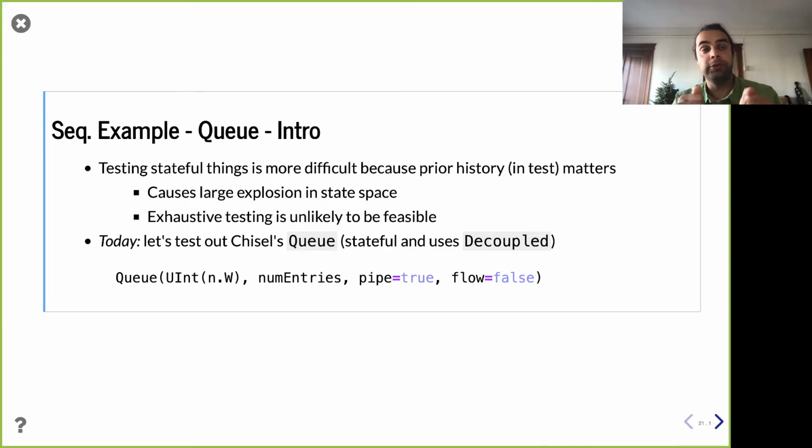So while you're trying to enqueue, the queue is full, but because someone's dequeuing, you can take advantage of space that can be made. Now the reason why it's not on by default is this now creates a connection between enqueue and dequeue, and potentially that's not something you want in your design for either critical path reasons or even combinational loop reasons. And so that's just a parameter we have on for today.